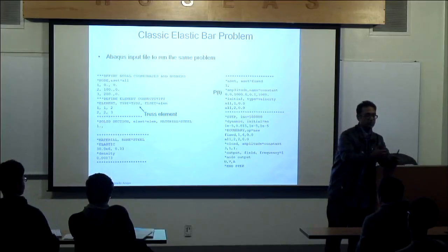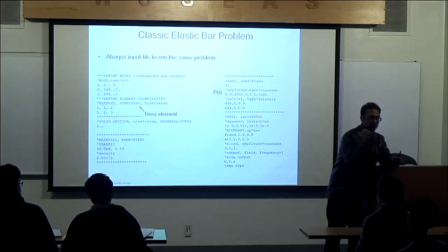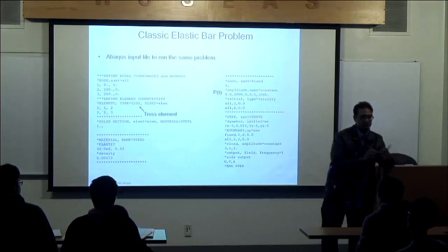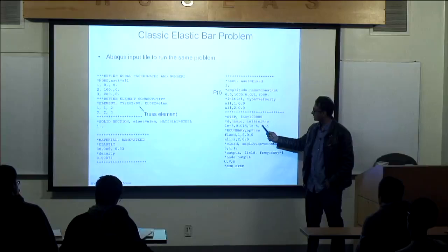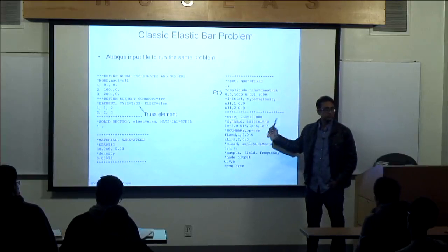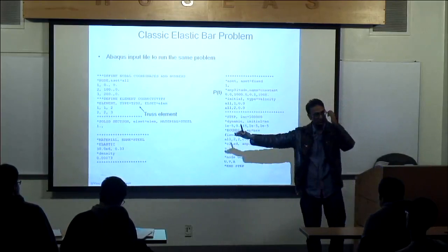If the solution doesn't converge very well, it will cut back the time step. I want to just maintain it at that number, 1e minus 5. This represents the maximum time increment, and this represents the minimum time increment. I'm forcing it to be the same as the initial time increment, the same delta t as I go forward.